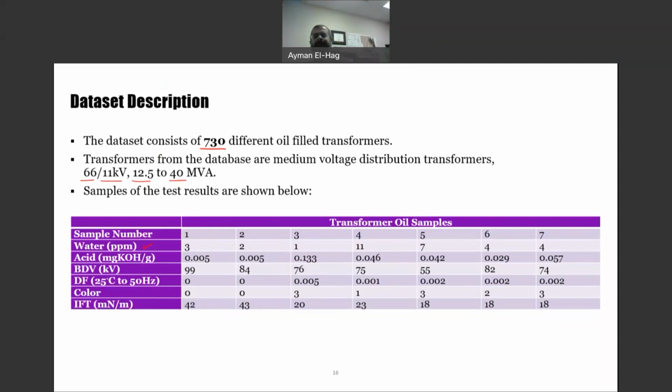Otherwise, if you don't understand the physics, you will not be able to understand the meaning of the results. And many times you've seen that results don't make any sense. I remember one time I was reviewing a paper, and the authors were measuring currents in microamps, and they were doing all this fancy classification. But the microamp is basically noise. It was not actual or capacitive current. It has nothing to do with the insulator.